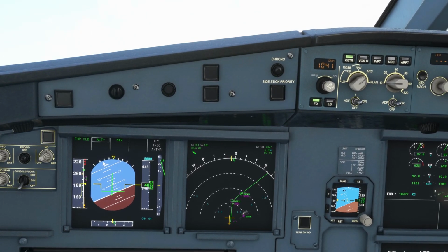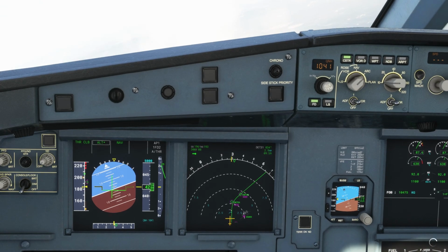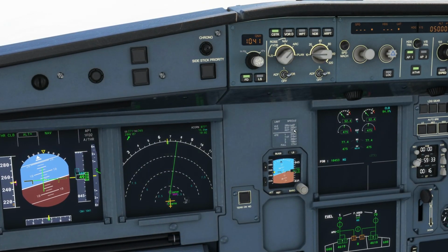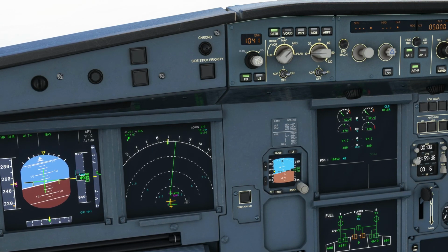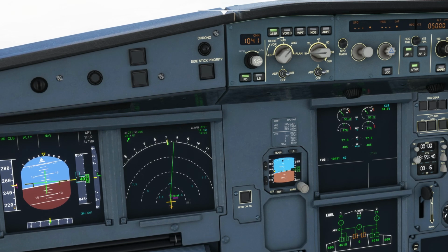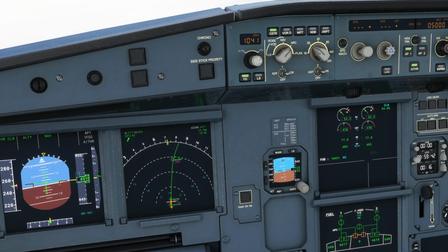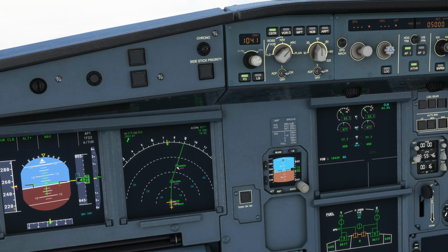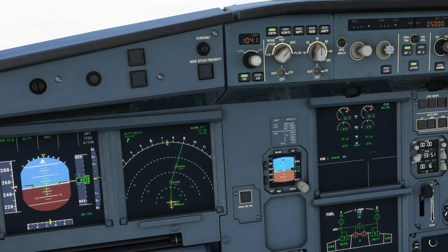We're getting closer to our 5,000 feet, so the aircraft will now start reducing its climb and prepare to level out at 5,000 feet. At this stage in our IFR flight, we are either constrained by that dictated on the standard instrument departure, or in this instance, the restrictions placed on me by ATC of 5,000 feet altitude and a speed not exceeding 250 knots.